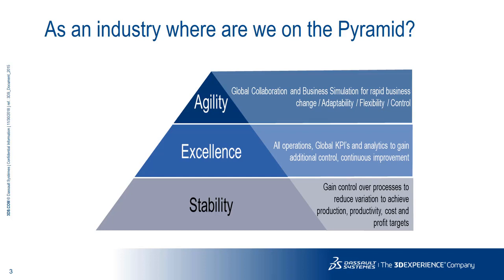This is where the Stope Optimizer can help. The Stope Optimizer, as I said, is new to Sepik 2019 and provides the mine planner the ability to automate the stope design process for strategic planning, analyse and determine the optimal stope shapes through the ability to rapidly generate and review results based on a variety of economic parameters and practical mining constraints. It allows rapid evaluation of numerous scenarios to develop a plan A, B, C, and so on towards finding the optimum plan.